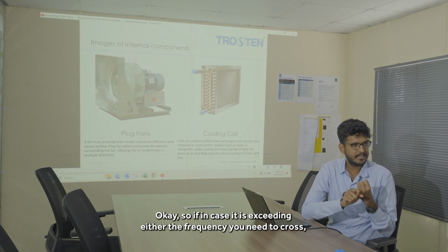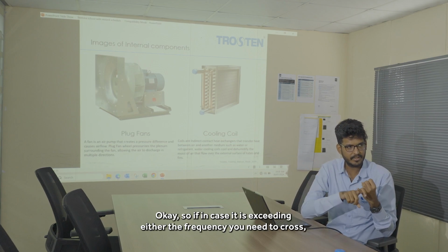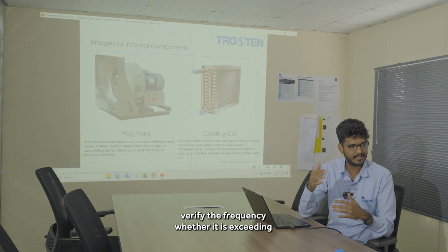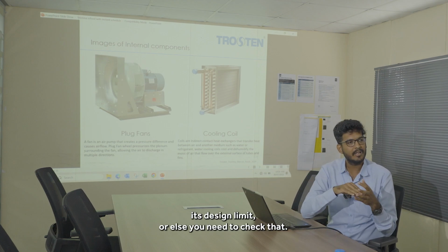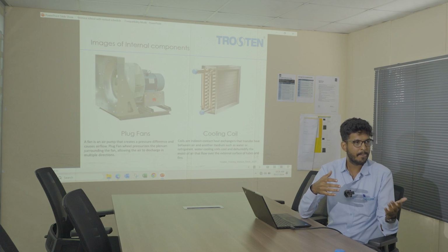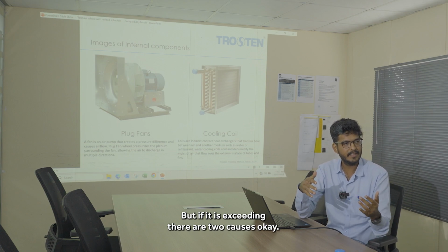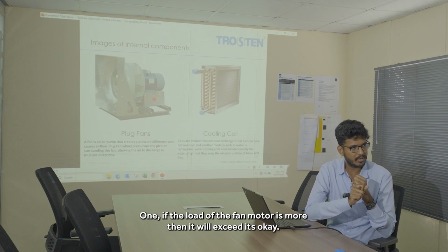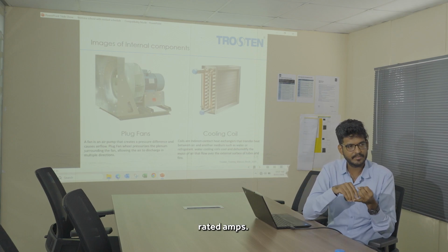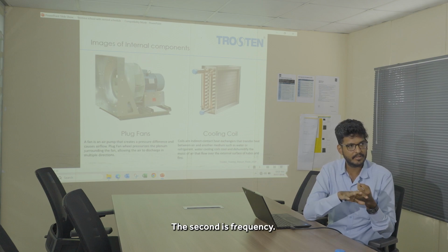Okay, so if it is exceeding, you need to cross verify the frequency, whether it is exceeding its design limit. There are two causes. One, if the load of the fan motor is more, then it will exceed its rated amps. The second is frequency. You need to check the frequency.